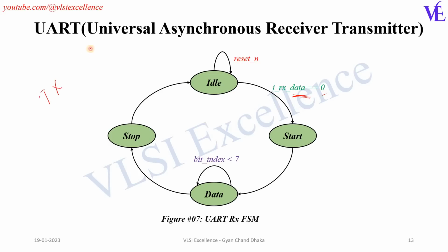So we have the UART TX and the UART RX controller. This is the UART TX transmitter and this is the receiver. This is the TX line, this is the RX line. The TX line gets connected to the RX line in the UART receiver. By default this line is held high. As soon as this line goes low, that indicates that the UART transmitter is going to start a new frame, or it is going to transfer some data. So the line will go low.